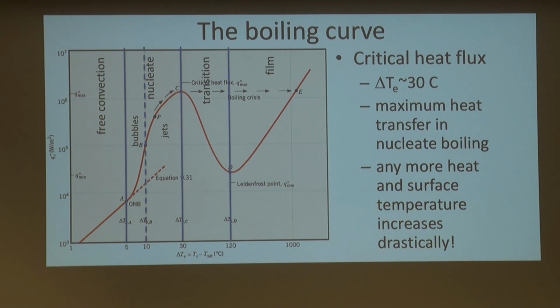Very interesting thing. Very important for everybody, because what this means is that, for example, if you're trying to boil water in a heat exchanger and you have flames, right? If you put more fire than the heat you can exchange in your boiler, you're going to end up melting the tubes, which, as a matter of fact, happens. Right?